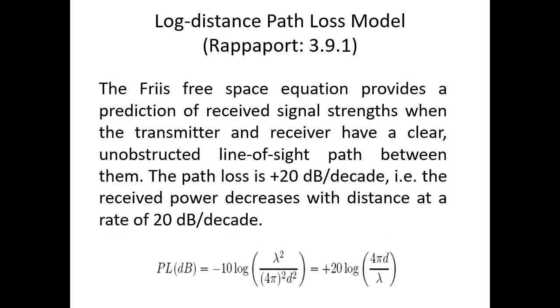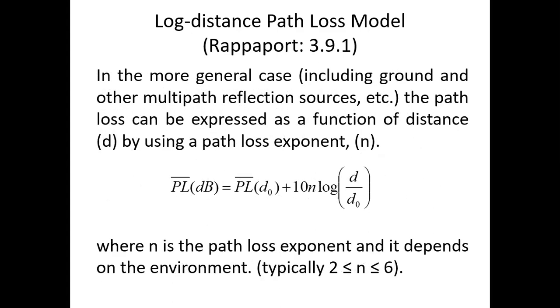We also probably discussed this log distance path loss model before. If not, then let me share it now. We had some derivation. I remember that we considered a path loss at a reference distance, and then compared to that, the loss was estimated for any other distance. So then you use a ratio.